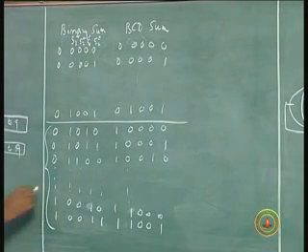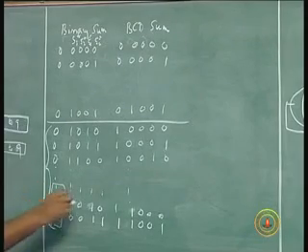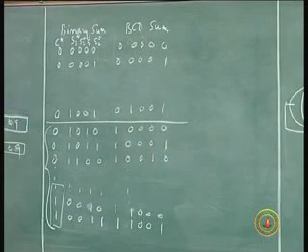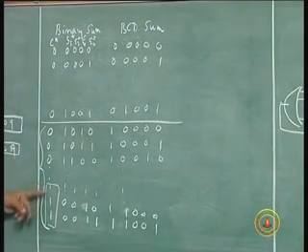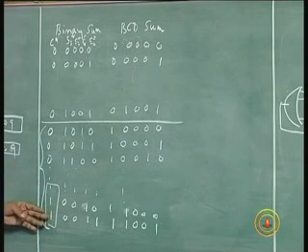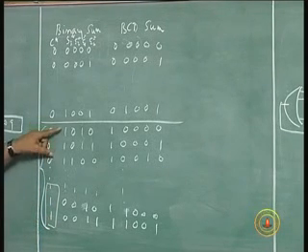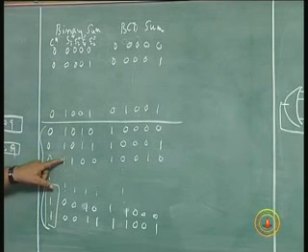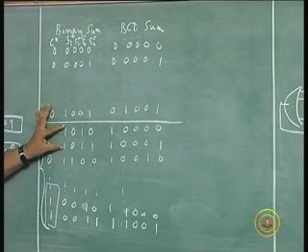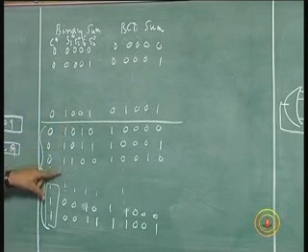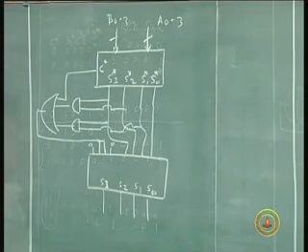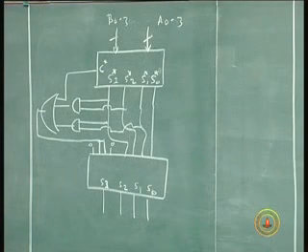Either this carry, which is the binary carry, this is C star. So I have to add 6 for all these cases where C star is 1, or when these two are 1, this and this bits are 1, or when this and this are 1. These first two terms are taken care of by this, then all the other terms are taken care of by these two, and the last terms are taken care of by these two. So I have to add this. We will call this the final carry, which is what is required.